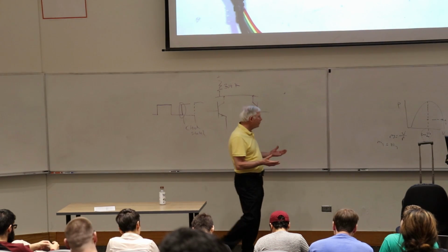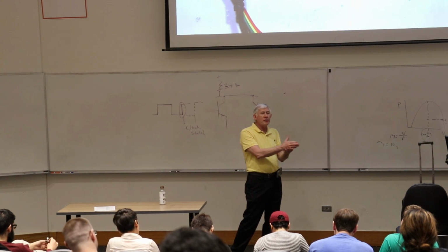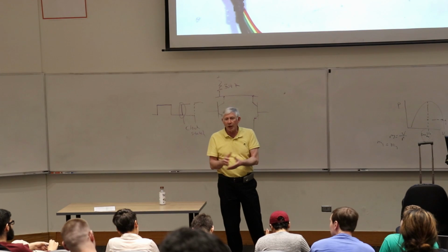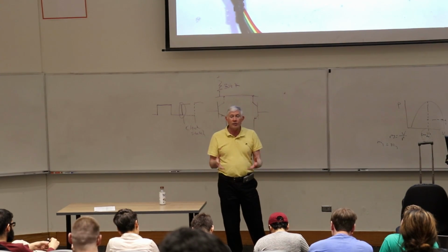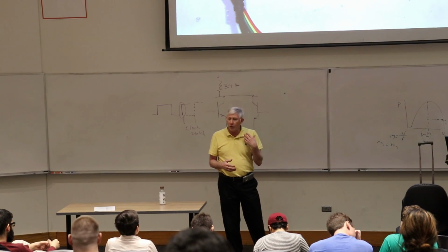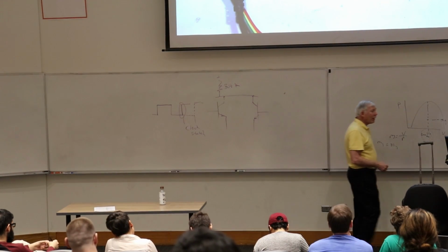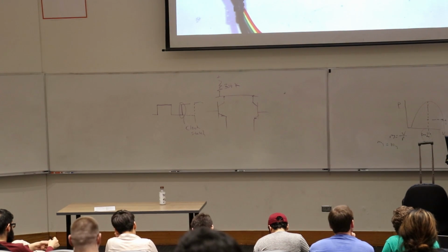So he's going to talk to each of these chips individually with an I2C line, so he can send out a different set of code to each one of the PICs, and then they can in turn program the little key, which is an I2C programming program. They're going to use the other I2C channel to program these individual little parts, and then they'll verify them, and then they'll send that information back to the master, telling it that, yeah, I programmed it and it's verified.